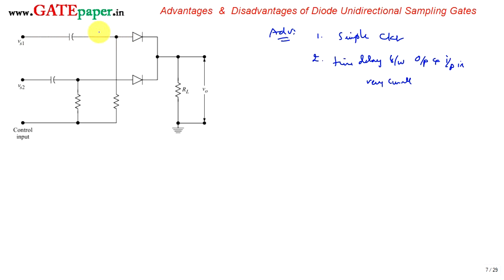The delay is very small, as the capacitor doesn't react to instantaneous changes in the inputs. So the voltage across the capacitor doesn't change. That means whatever changes you get at Vs1 will be affected on V0 directly at that instant itself. So the delay between output and input during the transmission path is almost zero, or very very small practically.